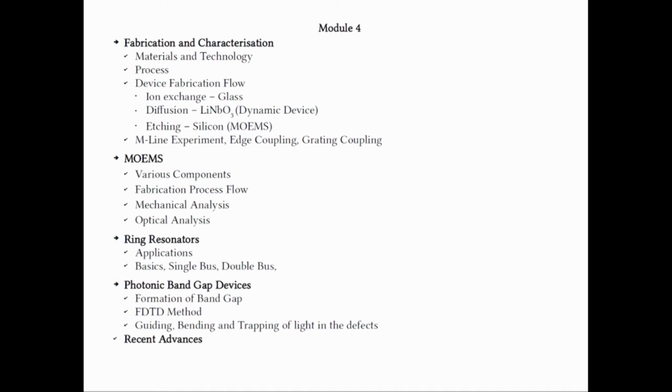One experiment we have discussed on the measurements, planar waveguide measurement, is very important to characterize the process, where we can estimate the refractive index profile, then the losses and many other factors of the planar waveguides. So, when it comes to the channel waveguide, we can couple it by using edge coupling through a fiber, and also more recently one of the most popular techniques to couple light into the optical circuits is by grating couplers.